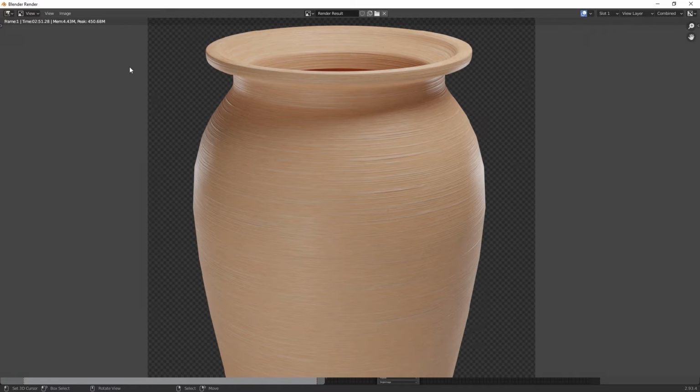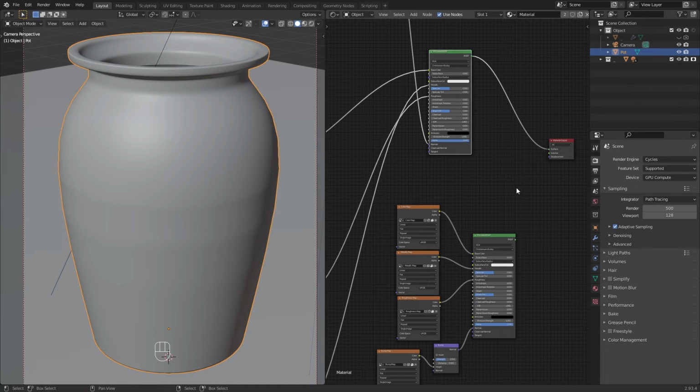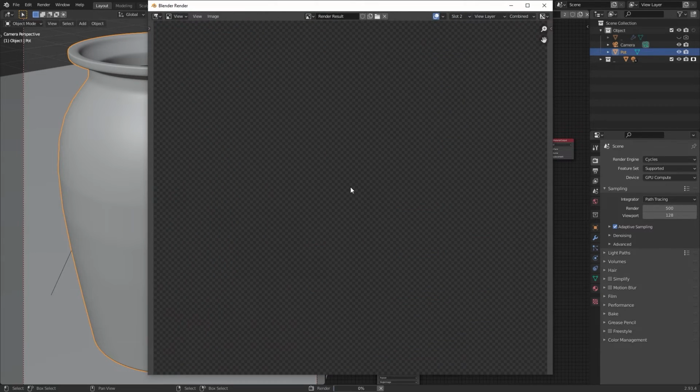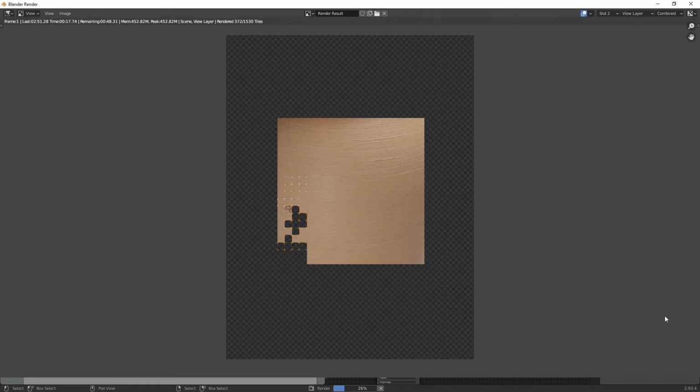So, first, here in the render result window, select slot 2 to get the result of the baked material. After selecting that, now close this window and connect the material output to the baked texture map connected Principled shader. And then render this now. Here, we use the same render settings for both renderings, so we can see how fast the baked material output is.